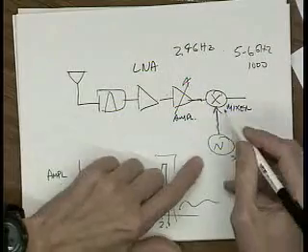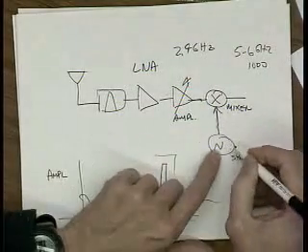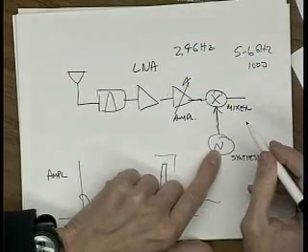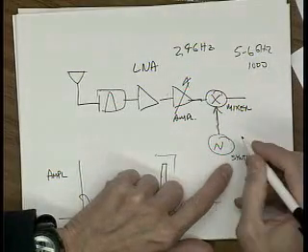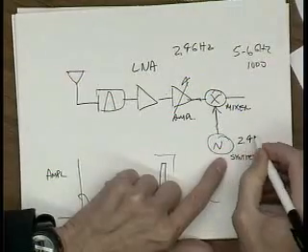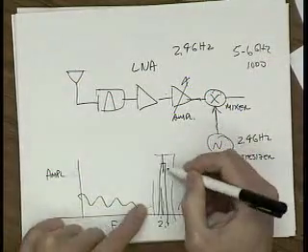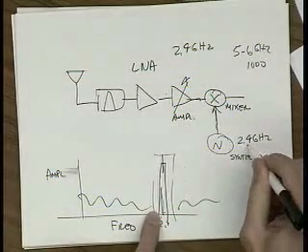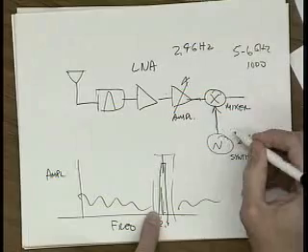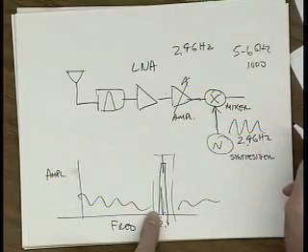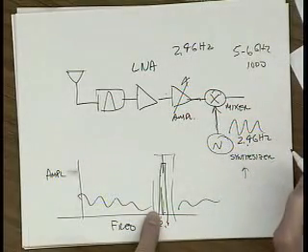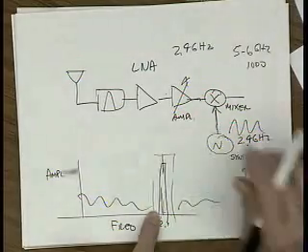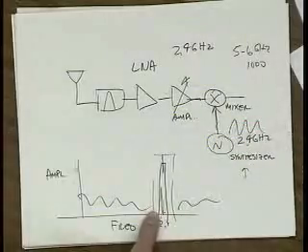What this synthesizer and mixer do is, you call this a direct conversion receiver. You make the synthesizer at 2.4 gigahertz, the same as the carrier of your signal. This is a sine wave at 2.4 gigahertz you have to create. This is a tricky little circuit design problem. Let me tell you, it's an interesting one. You use a bunch of strategies. It's a feedback circuit with a phase lock loop locked to a crystal, generally.